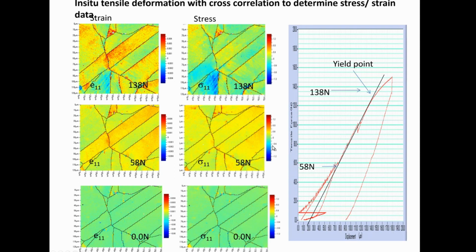This is the loading on the specimen, and here are just three snapshots of the information that one gets out of high resolution electron backscatter diffraction. We're looking at the strain in the sample, and that's being shown as a color now. We've superimposed the grain boundaries from standard EBSD. Now, the green here has a strain of 0. We're at the 0 load, and that's what you'd expect.